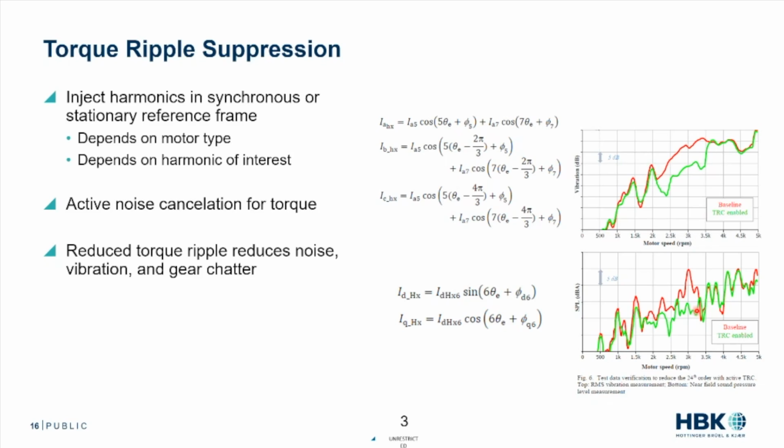But again, we need to be able to measure and control those, which I promise I'm getting to, the measurement. So we can do torque ripple suppression with harmonic injections, using our harmonics advantageously. Again, we're probably going to be at the cost of a little loss, but we have to look at what our end goal is.